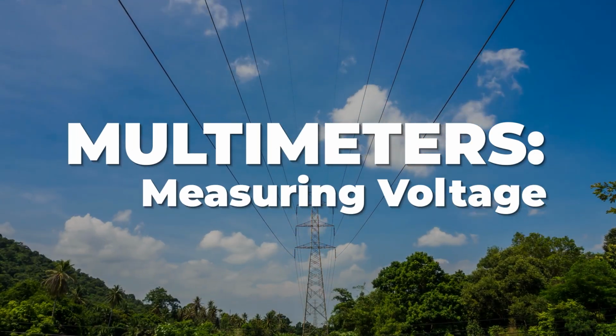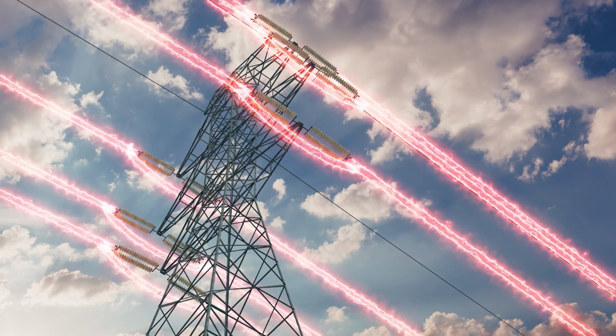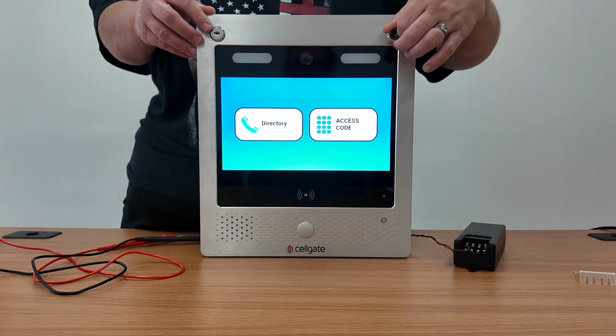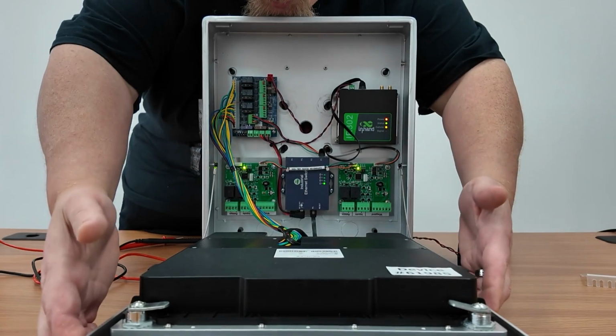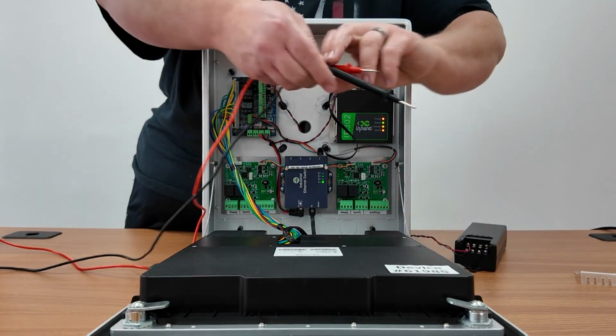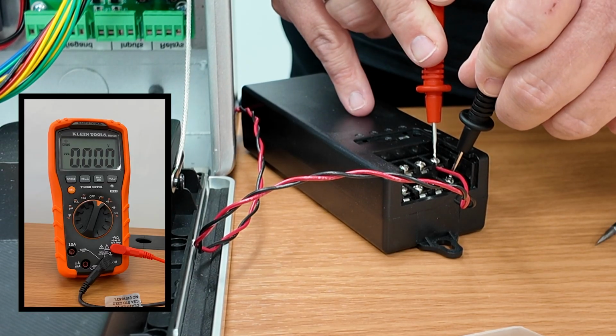Measuring voltage. Voltage is the electrical potential difference that causes current to flow. Before taking voltage measurements, ensure all connections are secure and check for blown fuses. Voltage measurements are often the first step in troubleshooting. Set the multimeter to DC mode and check the power supply voltage.